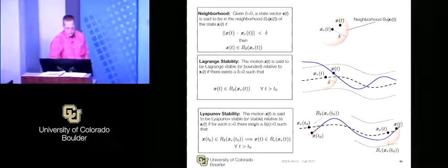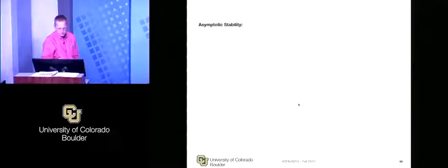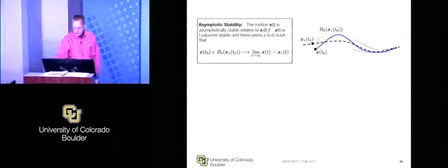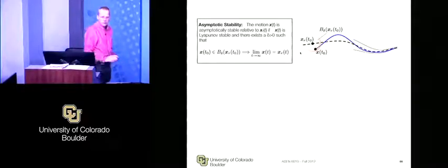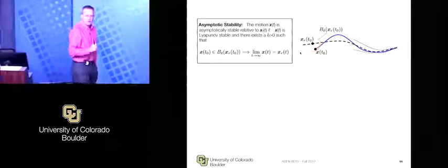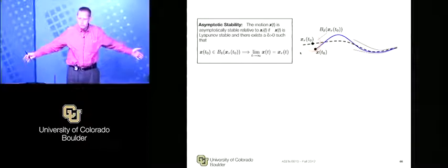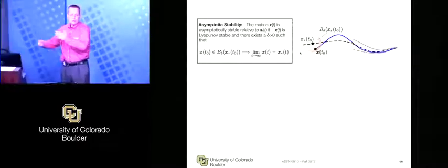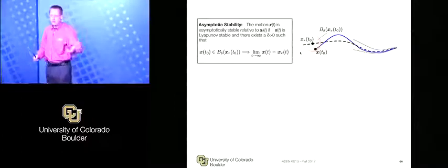If we do converge, what do we call that kind of stability, Franklin? Asymptotic. That was asymptotic stability. So here the final ball shrinks to 0. Now, all these stability proofs I just mentioned were local stability. That means there's some initial neighborhood that you can guarantee. If you start out within 1 meter, things will converge. If you start outside 1 meter, you're on your own, right? It may converge, it may not. In fact, it may diverge.